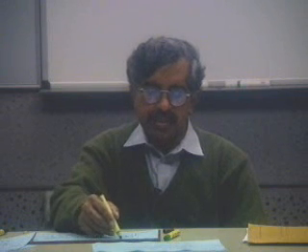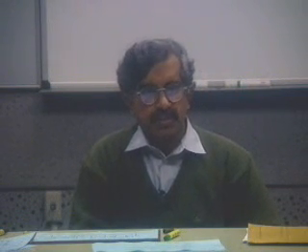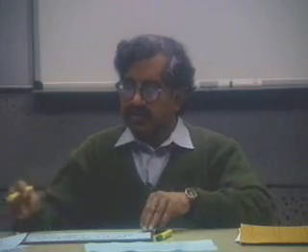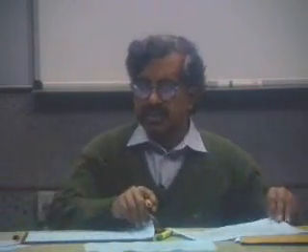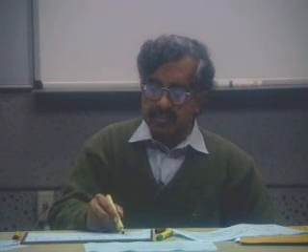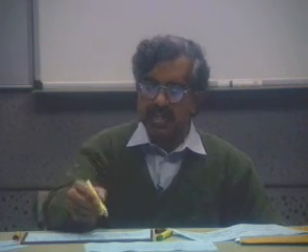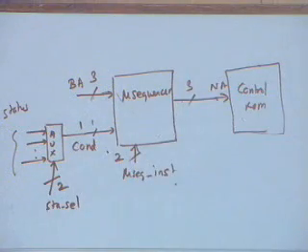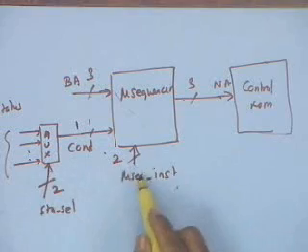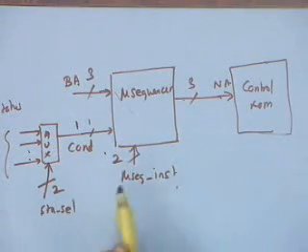That means I will have n equal to 3, which is nothing but the log of the number of microinstructions. So this n is also 3. Now this completes my input-output design of this. This I have 2, this of course is 1, this is going to be 2. Of course this doesn't come from the sequencer, it comes directly from the microinstruction format. We will see that. This one is 3 and this one is 3. I need to generate 3 next address lines based on 3 branch lines, 2 microsequencer instruction lines and 1 condition.